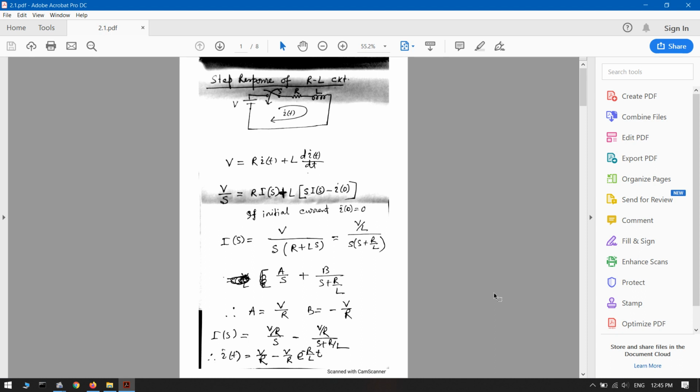So far, three cases we have discussed, all three are step response. Now, consider one more different response, like impulse response of RL network. That derivation also I have given to you. Impulse response means here input voltage will be an impulse function, some value with delta of t. Suppose here we have considered E into delta t. This is the voltage, E into delta t, and it is applied to an RL circuit.